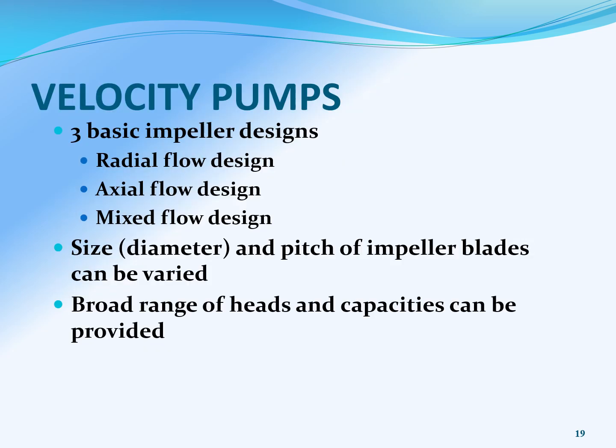When you're talking about velocity pumps, there are different impeller designs because it depends on what you're trying to pump. So you can have radial, axial, or mixed flow designs. Again, it just depends on what it is you're trying to pump. The impeller that you select is just as important as the type of pump that you're selecting. But they can be used for a broad range of heads and capacities.